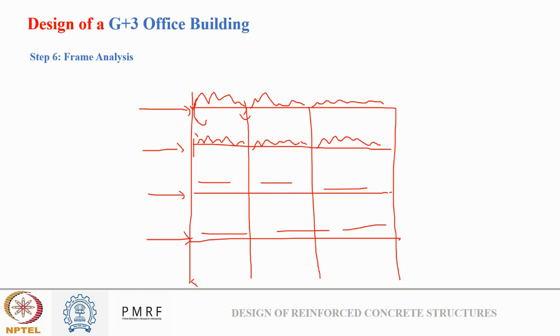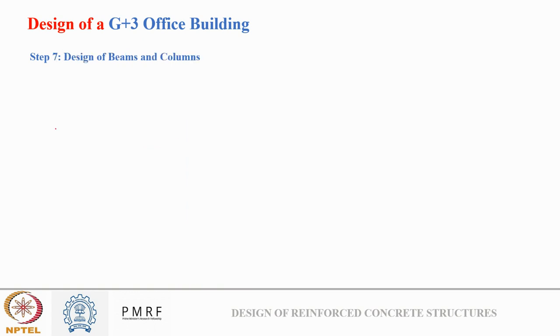We know the lateral, horizontal and vertical dimensions, and using standard codes and practices, you can calculate the bending moment and the shear force generated across each joint. Once we know the bending moment and the shear force, we can design the beams and the columns. So, simple beams. You know the moment.